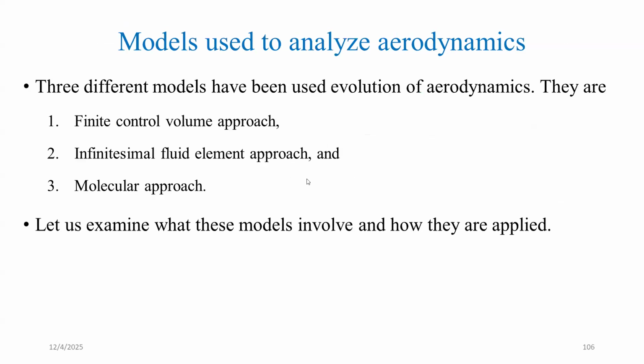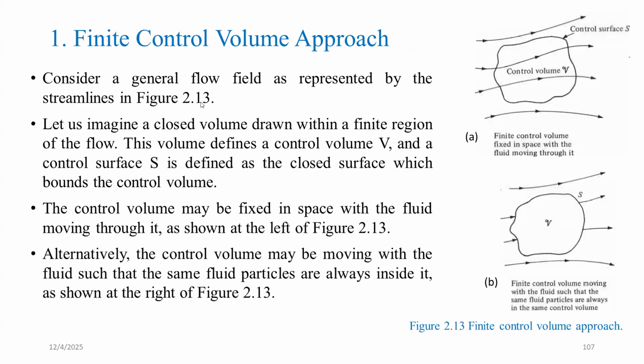In order to analyze the fluid flow, we have to use some among the three different models which are used in aerodynamics. One is the finite control volume approach, the infinitesimal fluid element approach, and the molecular approach. These are the three approaches on which we analyze the flow field. The first one is the finite control volume approach.